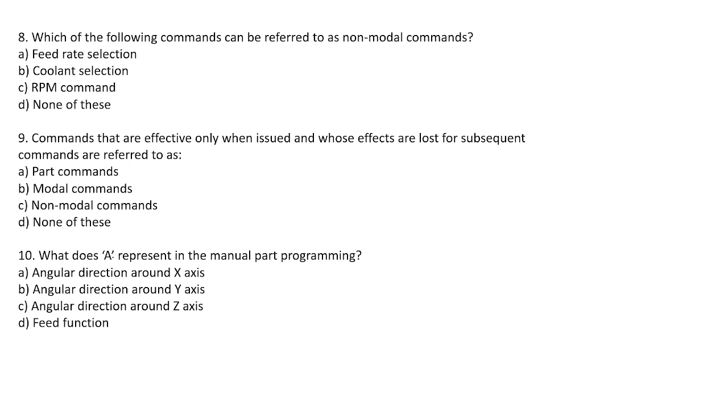Basically, by referring to that, the commands issued in NC programming are referred to as modal commands and non-modal commands. Modal commands include feed rate selection and coolant selection, and another one is non-modal commands.